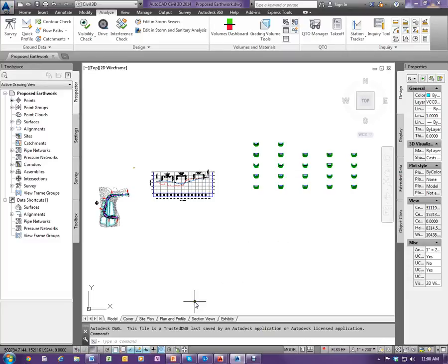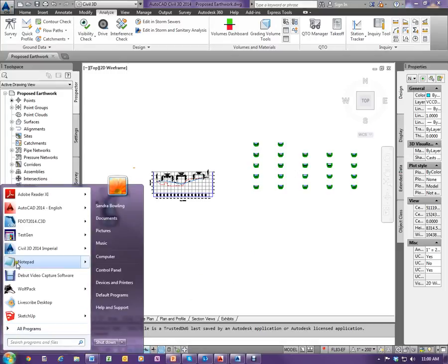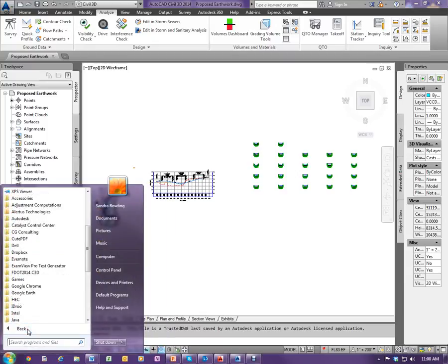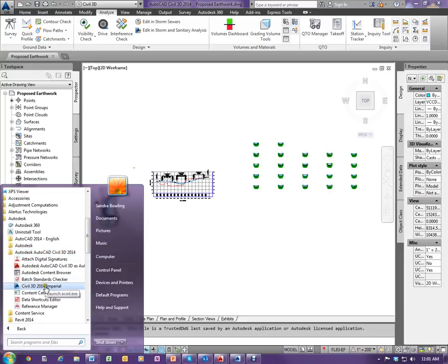In this video, I'm going to show you how to create earthwork quantities and material quantities for your roadway, like asphalt, subgrade, base. Now, when you open up the drawing, I want you to open up the Civil 3D 2014 Imperial. So you go to All Programs, Autodesk, Autodesk Civil 3D 2014, and you'll open up the Civil 3D 2014 Imperial. All right.